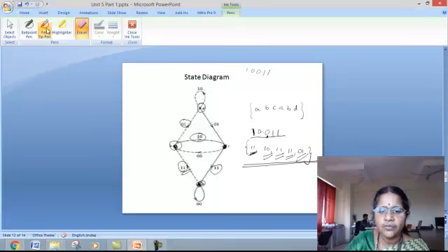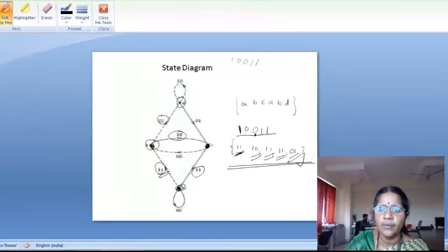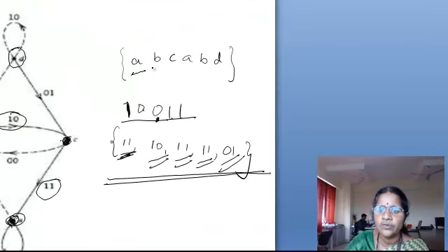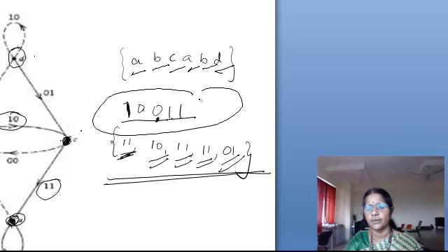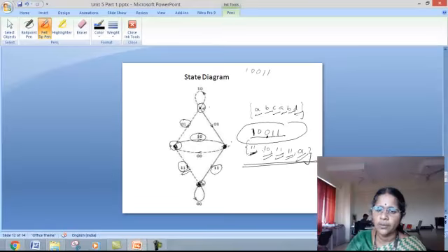And now the path followed was first it is A, then you went to B and then to C and then to A and here to B and finally to D for the message sequence taken as 10011. This is the path followed. So once you draw the state diagram, it is easy to encode without going for those polynomial computations.